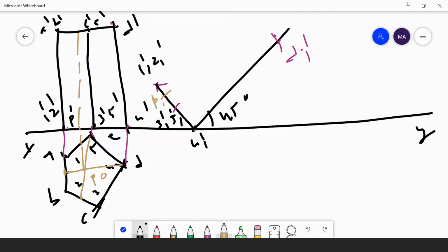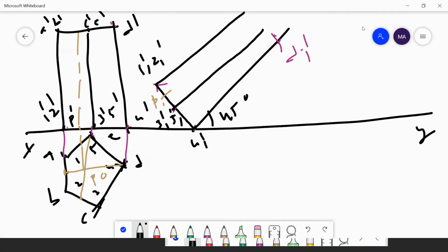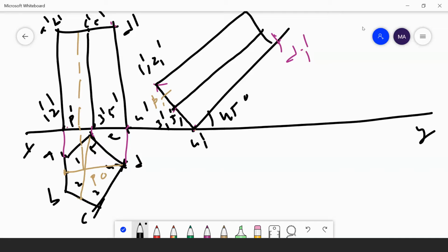Then I have projected all the points. I have drawn a parallel line to this line using the drafter. Understand? Then up to here, up to D. Then I am drawing the line like this. Or else you can measure it and cut. No need. Directly you can draw a perpendicular line to this 4D.